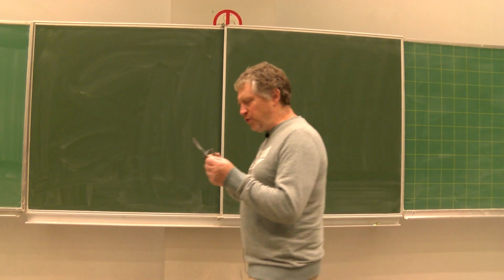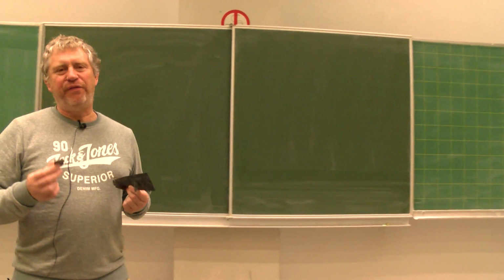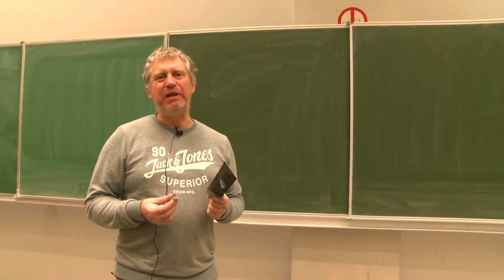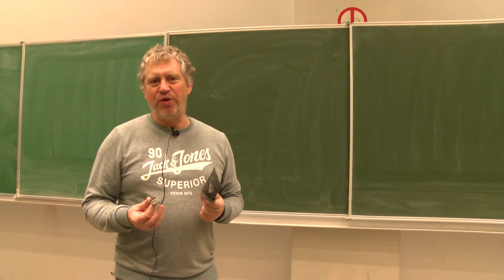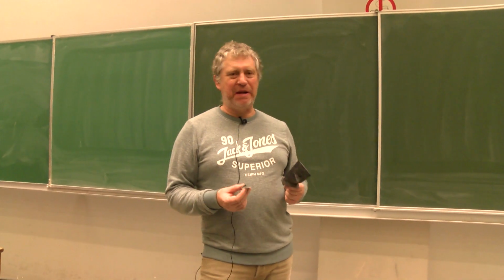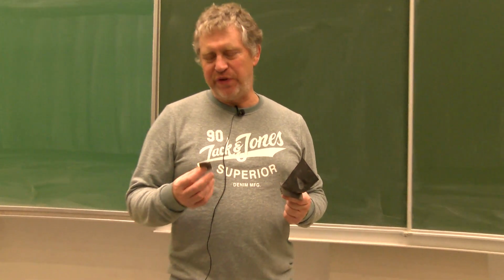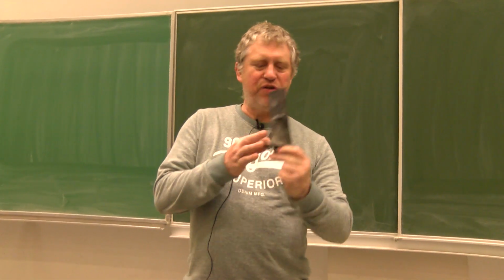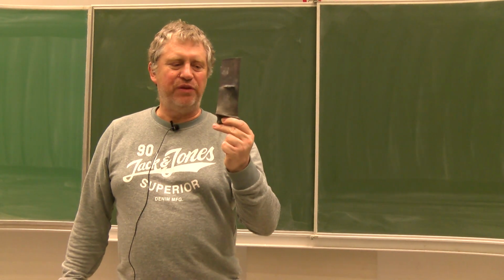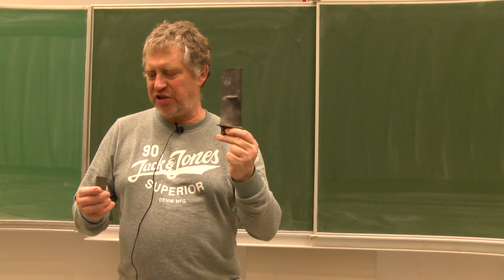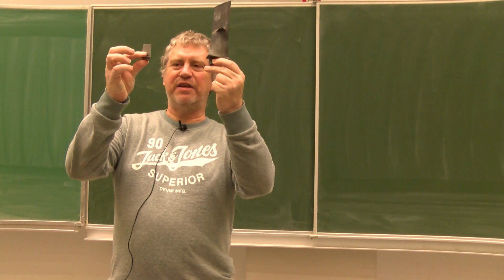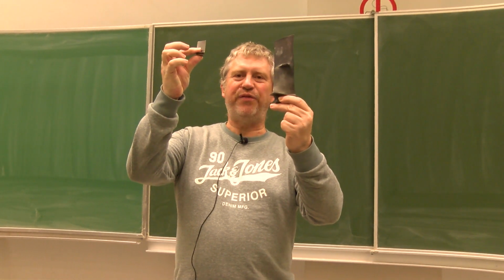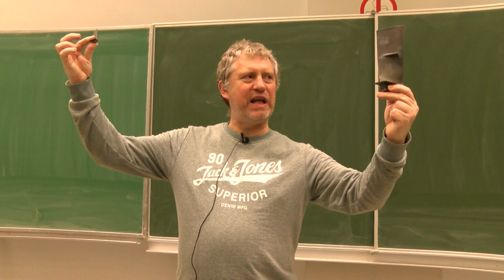So, I wanted to show you also blades of different stages in order to show you the huge difference existing between H or H over C, because we like non-dimensional parameters, so H over C is non-dimensional, between a first stage, you need to show it like this, the flow is coming from there to this direction, and the last stage, where you have, that is something like this, so at this position. So you see the huge difference existing between two stages.